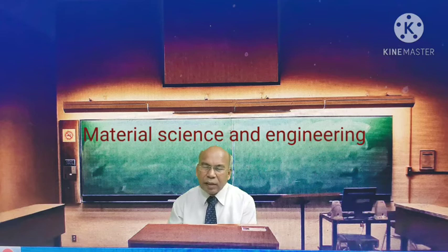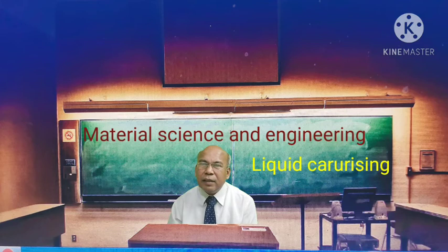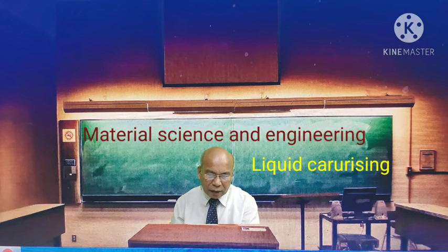After the particular period of time, it's removed, and the surface part alone is hardened for a particular desired depth, while the inner part remains soft, not hardened. Then liquid carburizing, another method.